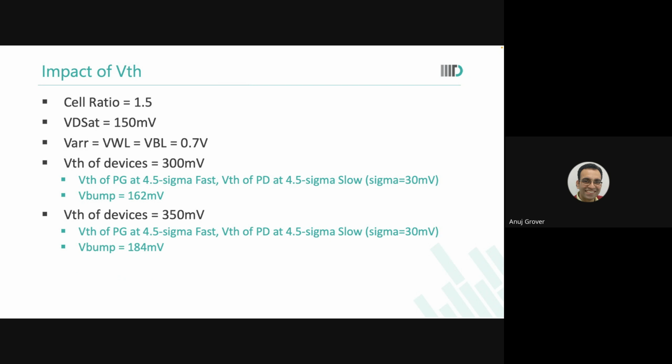So what does this tell you? That if you have to design a very low voltage memory cell or a very low voltage memory, you will probably want to use an SVT memory cell. It will be more stable. Now, what we also do is that, do I really need the full cell to be SVT? Or can I just do an SVT on the PMOS?